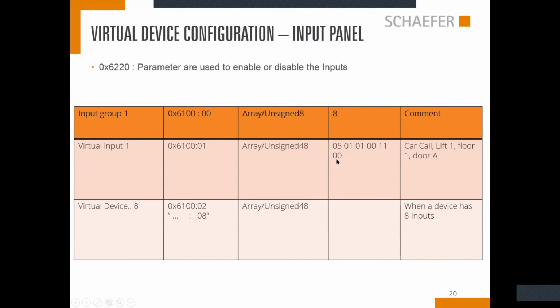For a virtual input, this status bit is quite important for technicians in the field for debugging. By using the Lift CAN controller or the bus, they can read the status of each bit. So for example, if this virtual input is high, then here we would get a status message of 01. So let's go on to the next slide.